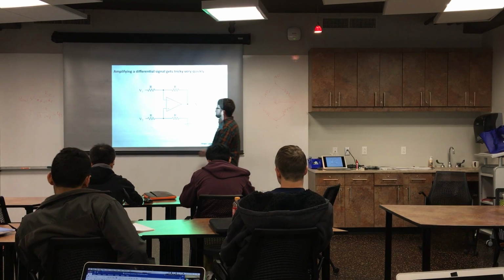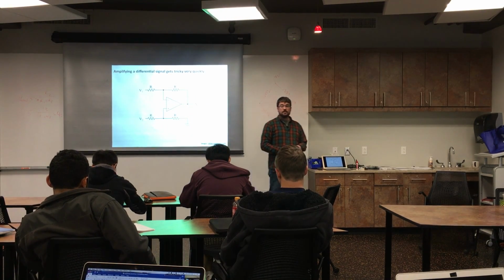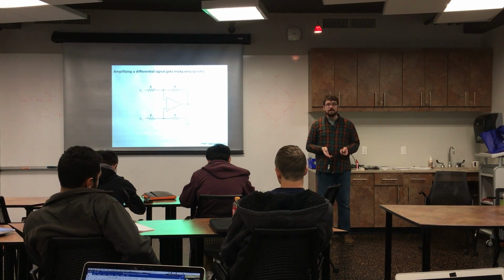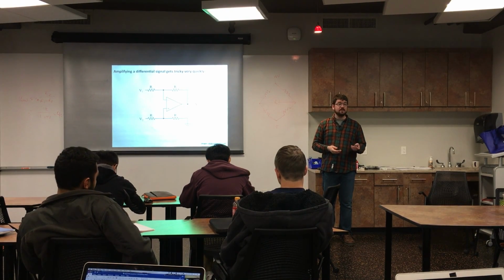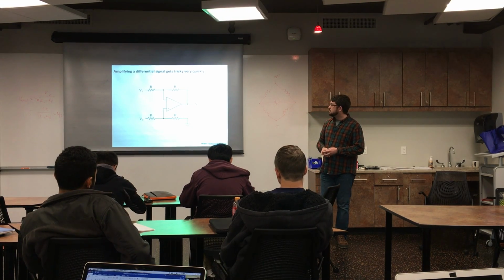Even 1% resistors, 1% tolerance aren't really good enough for this. You need 0.1 at worst, 0.01 is better. And those resistors can get expensive. So it's not really an ideal setup.